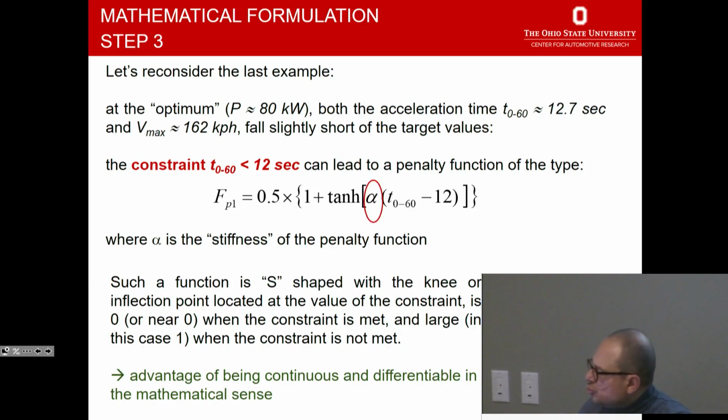So what could you do to impose constraints in such a way? And remember, we talked about this constraint when we talked about ECMS. We said, hey, I want to make sure that my state of charge stays around some target value. If it deviates too much in one direction or another, I want to penalize that. Okay, that's ECMS. So we're solving an optimization problem. And we had selected a cubic function for that one. We normalized state of charge around 1, and then we created a cubic function that...